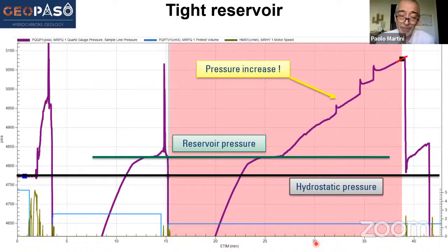It has a little bit of flexibility, but if you have a lot of hole ovalization, you will never get a seal. In terms of breakouts, you don't have the ability to orient your MDT tool or FT tool when you are taking pressures.